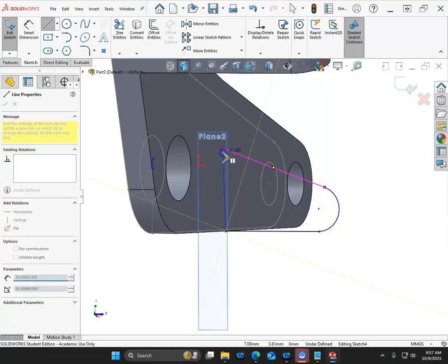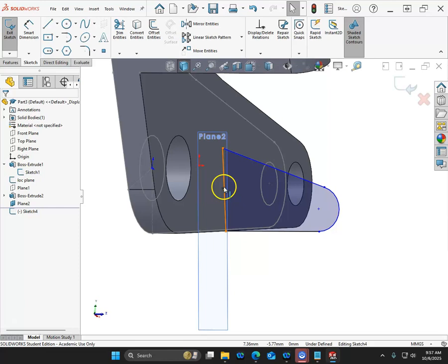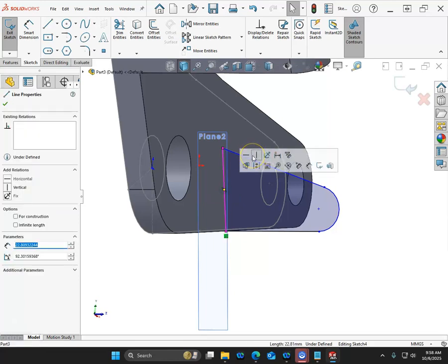And I'm not sure where that's going to line up. So we'll pull those two together and just make sure that that one's vertical. Select, Control, Select for tangency. And since we're just kind of cruising along here, we'll put in the circle so that I can hide the plane, and then Control 8 to get back into the geometry.